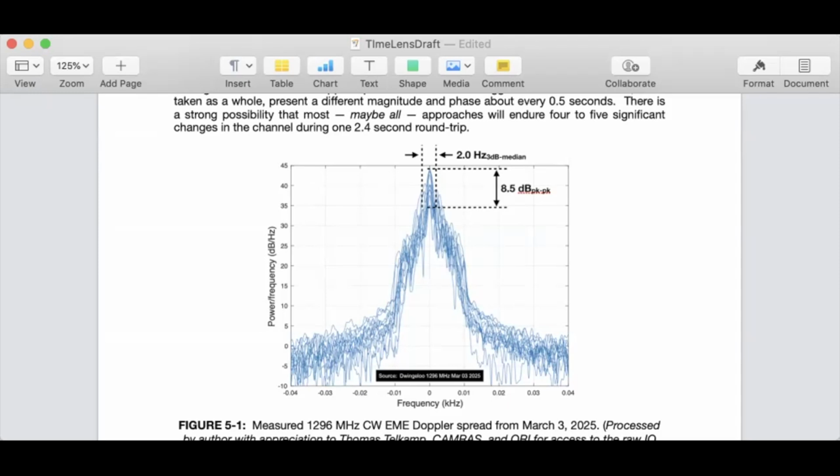Okay. Yeah, it's not something that I knew, not being an EME operator. This is really interesting because I think the assumption is that the moon is not rotating, but it is, and the libration actually is a factor in visual observation. There's a target list for visual observers in astronomy of the moon, and number 50, the hardest one to get, is a feature that's only visible at certain times because it's right on the limb, and it's only visible because of libration. So it's a significant enough factor to even enter into visual observation of the moon. When I think about it, it's really not that surprising that we have this factor here. And yeah, this actually does affect the coherent modes quite a bit, like you said.